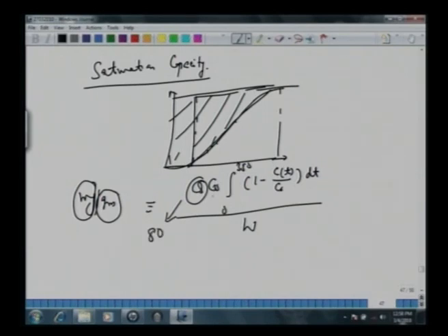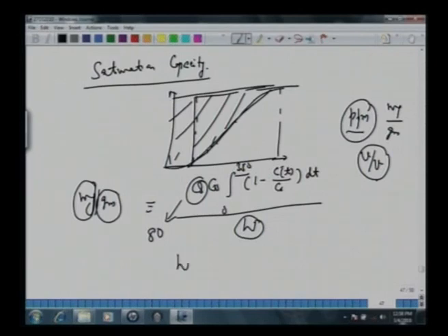This C0 we know, how much ppm we have. We can convert this ppm in the gas volume to some milligram per gram. For the gas, this is volume by volume. One can make some stoichiometry here to convert this to milligram per gram as well. C we know, that's the response. C0 is again known to us. We can integrate from 0 to 350 minutes. What is the total amount of adsorbent we have used?